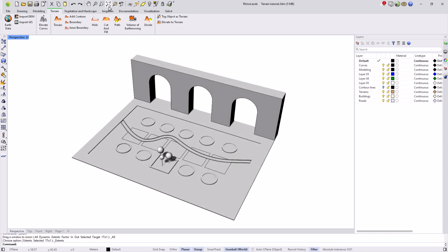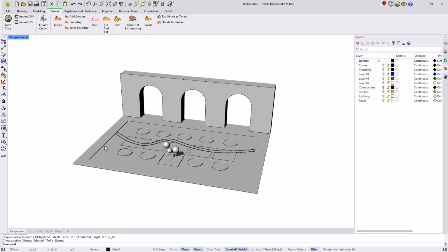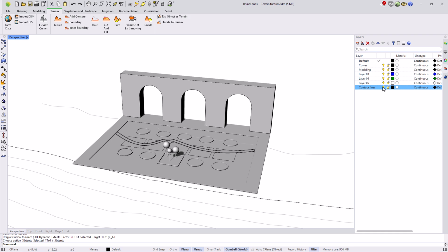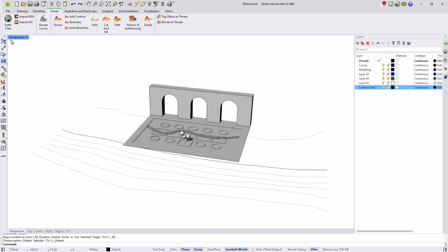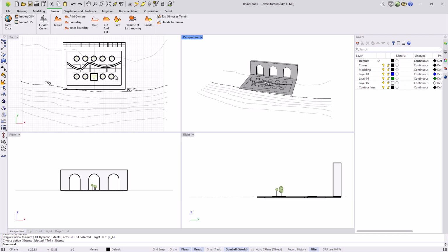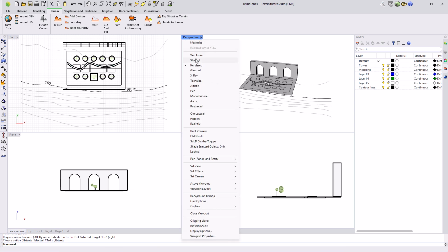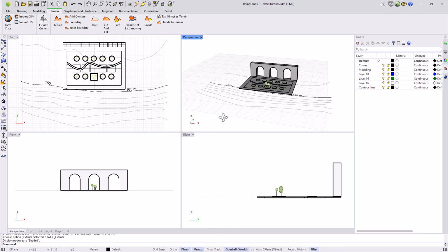For the project we're shaping, we're going to create a terrain manually from drawing curves. Raising curves allows you to generate terrain from curves, lifting them according to an increase in height. It's useful for transforming contour lines or level curves into a 3D volume. To generate the terrain for this project, I have a series of topographic curves. If you don't have a terrain to work on, you can just create a series of parallel curves to test the following commands.